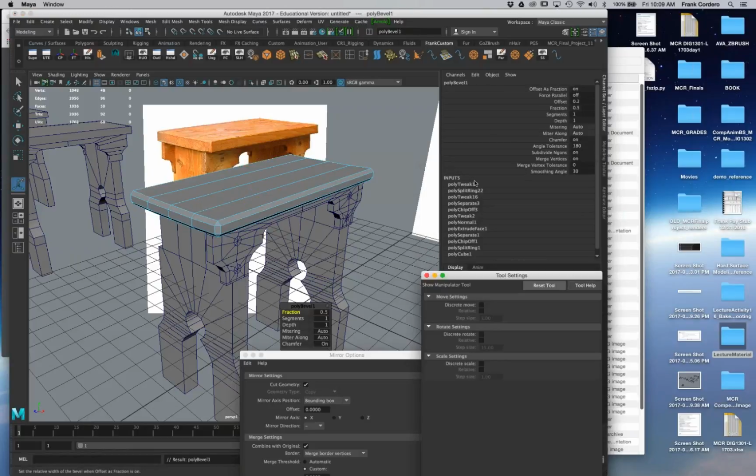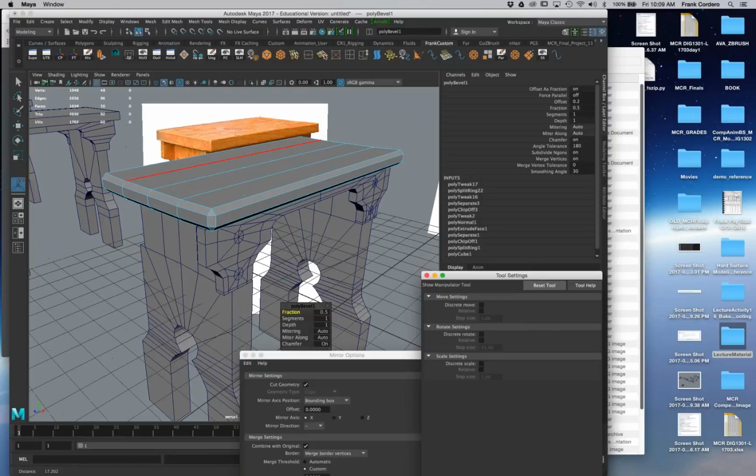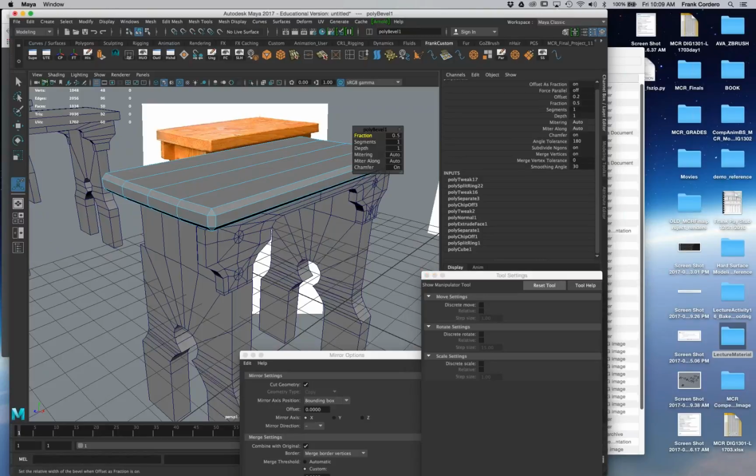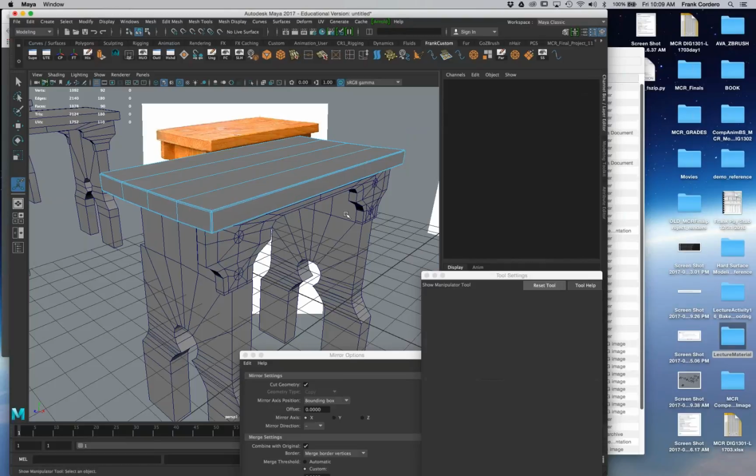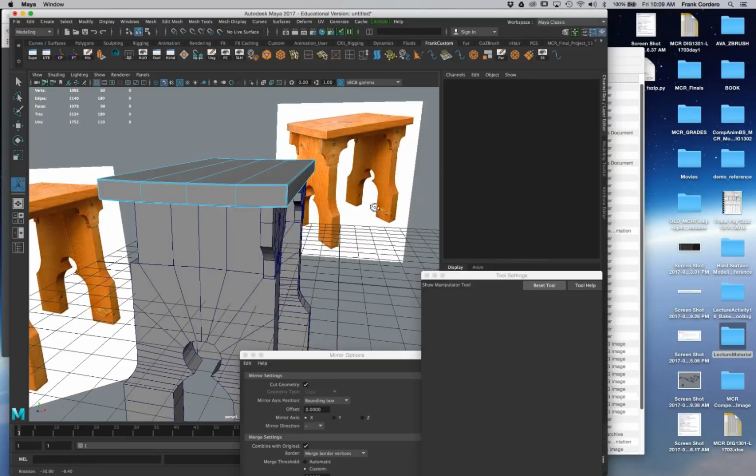As a matter of fact, that's too big compared to the reference. So I've got to go ahead and make some tweaks to this bevel. Let's get the size right first, and then let's get the segments. We're going to need a few, so let's try 2. Might make it just a touch bigger, but not by much. Control definitely. When you want micro adjustments, hold down Control while you're sliding these adjusters. Okay, so there you go.